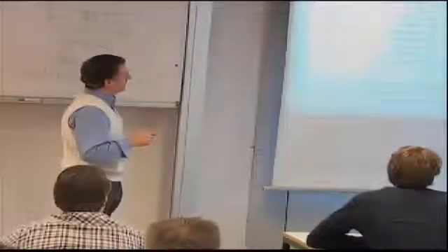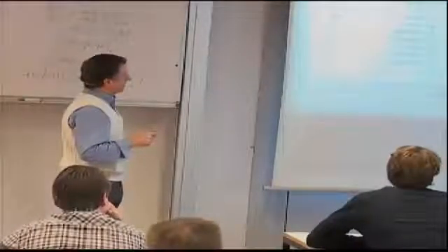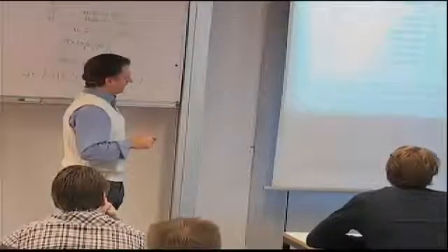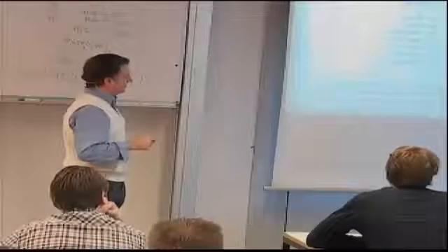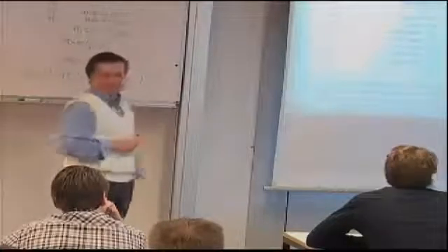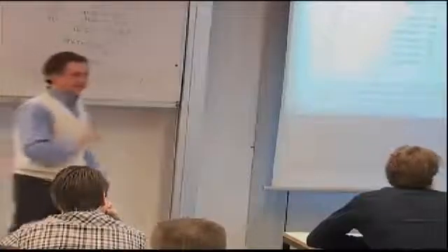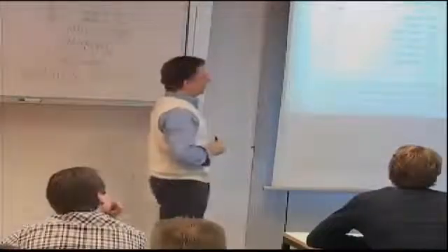I'll give you material properties. X is parallel to the fibers for the material we are talking about. Y perpendicular. This is Poisson's ratio, shear modulus, thickness of the ply, and then tension compression parallel to the fibers, tension compression perpendicular to the fibers, and shear. Now that's classical laminate plate theory, basically, and first ply failure, and a little bit of math to give me the shape of W.